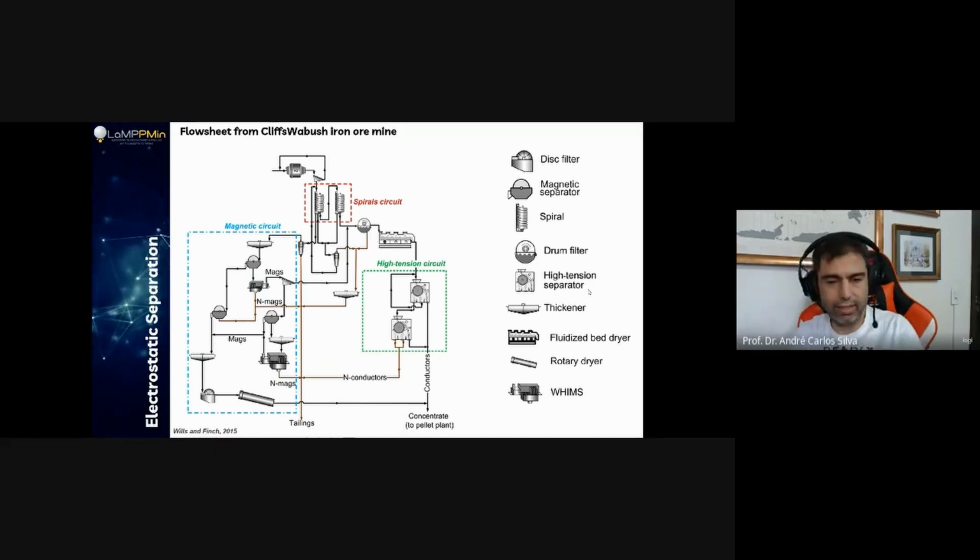Okay, you can't do flotation in space. Even on our planet, there are some places where we can't do flotation, at high altitude. If you go to the Andes, for example, Peru or Chile, and you try to perform flotation 5,000 meters high, you just can't do this. The bubbles are not going to work as you expected. So you have to take all your material down the hill, and then you can perform flotation.